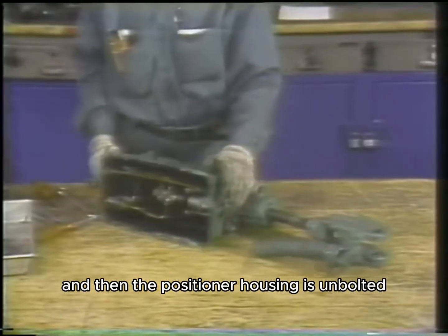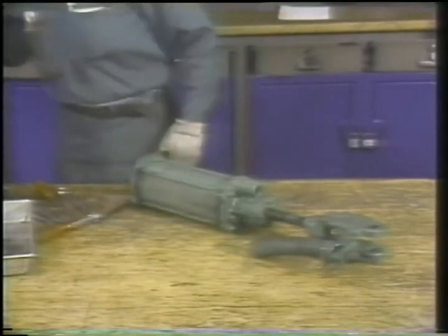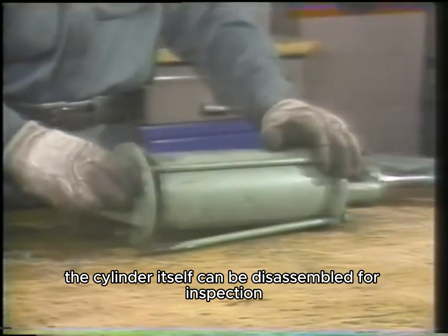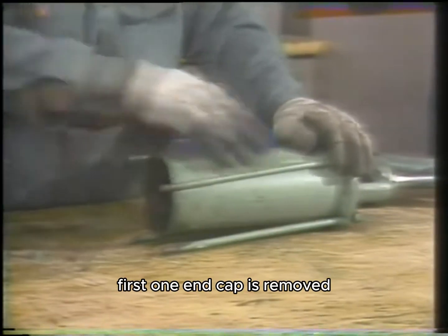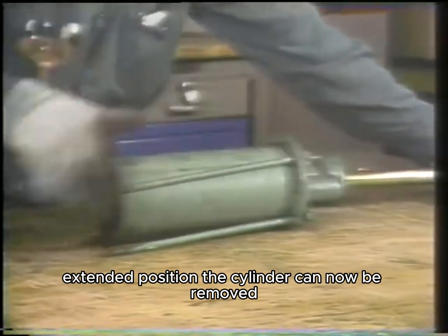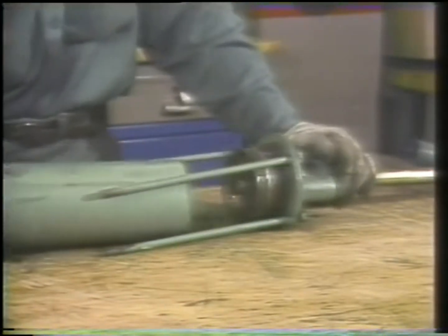And then the positioner housing is unbolted and removed from the cylinder. Now the cylinder itself can be disassembled for inspection. First, one end cap is removed, and the piston rod is pulled to the fully extended position. The cylinder can now be removed, exposing the internal parts.